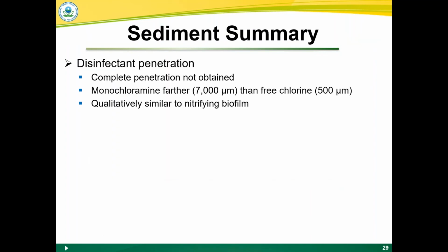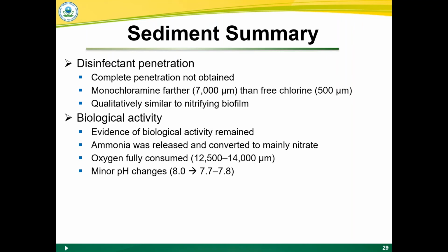Just a quick summary on the sediment. We never got complete penetration. Monochloramine penetrated further than free chlorine. But qualitatively, we're similar to what we saw with the nitrifying biofilm in terms of the two oxidants here. One thing that was remaining was definitely biological activity indications that remained throughout the entire study. We mainly got complete nitrification. The oxygen was fully consumed in the sediment.